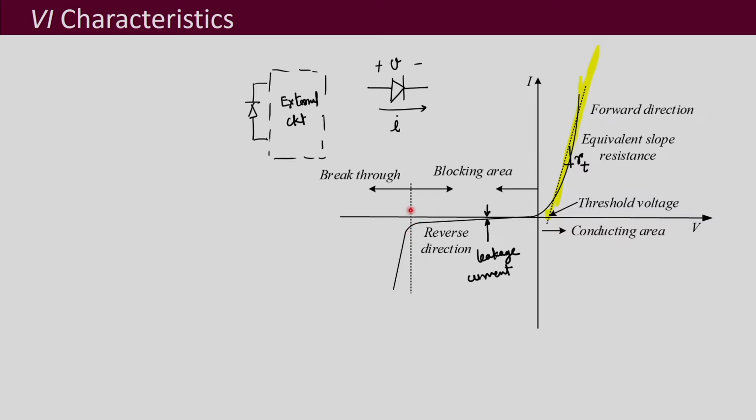So, this is the limiting voltage, or the blocking voltage of the diode, which you will be seeing in the data sheet. This part is the blocking region, beyond that it cannot block, and this is your forward bias region, the conducting region, where once the voltage exceeds the threshold voltage, the current starts to increase very rapidly. The current can be very high and is limited by the external circuit. You may be familiar with this, you might have studied this before.